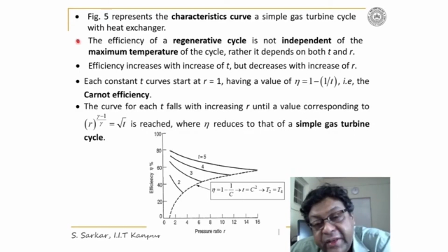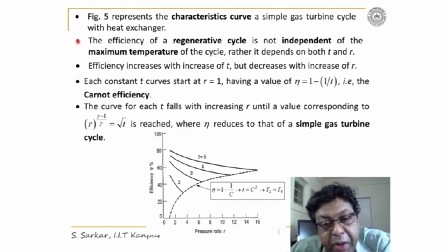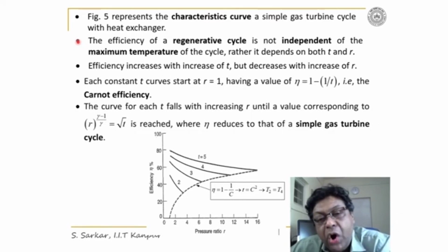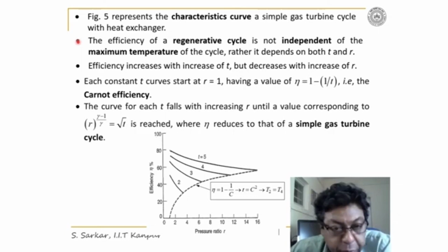Here, efficiency is not independent of maximum temperature of the cycle. Rather, the efficiency of a regenerative cycle depends on both temperature ratio and the pressure ratio.